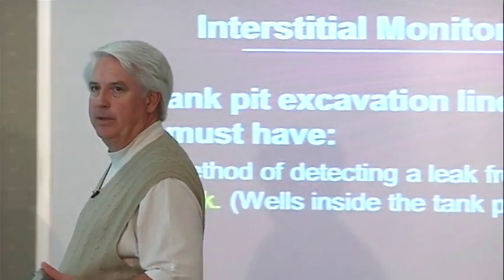How would you handle stormwater in case that doesn't work? I mean, if you have a big rain event, wouldn't it fill up that? Yep. And once you get into a situation like that, it's also going to try and lift that tank up out of the ground. There were a bunch of those with Katrina. There were so many underground tanks that just came blowing up out of the ground due to the buoyant forces of the water down there lifting them up. I mean, just bust the concrete and get them on the surface.